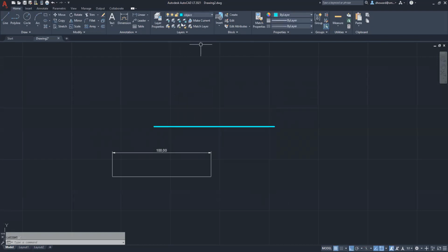And yet my construction line, let's do that. So there's that. It is thin, and let's do one of the in-between lines. The dimension line here was an in-between line. So you can see those are the three line weights I have: 15, 35, and 53.